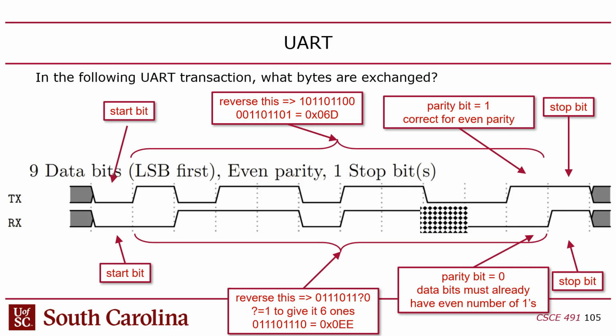Okay. All right. So this just points out what's going on here. Start bit, data bits, parity bit, stop bit. So what's the challenge? If I ask you this on a test or a quiz, the challenge is to count those bits, being careful not to include the start and the stop, which may be more than 2 bits if there's multiple stop bits, right? So that's the challenge from your perspective: figuring out which bits to count for the parity calculation. Any questions about that?